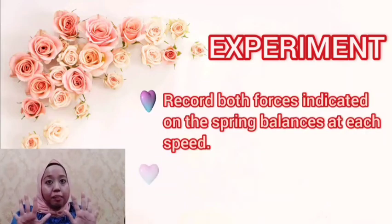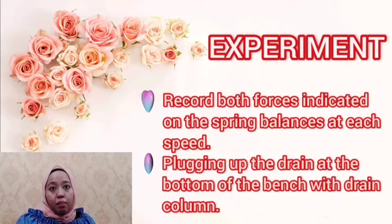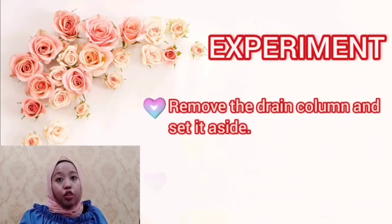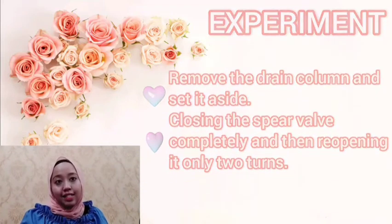The 10th step, plug up the drain at the bottom of the bench with the drain column. You have to make sure the rubber gasket is placed between the drain column and the drain. After finishing recording the flow rate, remove the drain column and set it aside. Don't forget to reduce the flow rate by closing the spill valve completely and then reopening it only 2 turns.